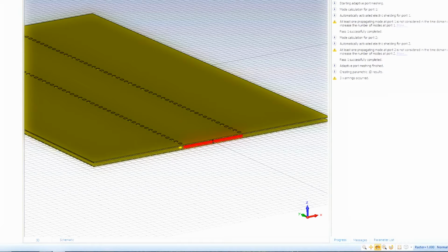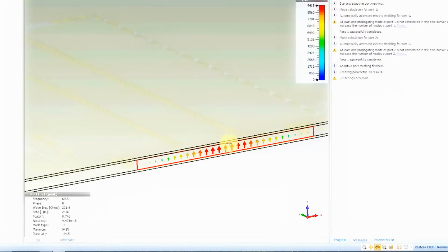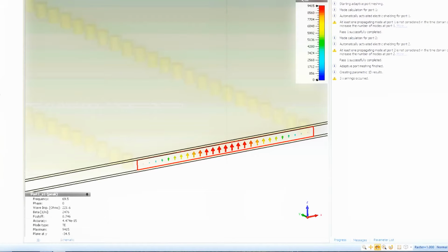Now, to see what it's got here in the 2D/3D results, port modes, port 1 or port 2 will be the same, E1. Now it'll plot me a little bit of an electric field, and that looks exactly like a TE10 mode. You'll notice here that the F cutoff is 8.7. So that means 8.7 gigahertz, and my SIW is far too wide if I wanted to go for 56 gigahertz. Similarly, E2 means the second mode. Now the second mode that will propagate, because the SIW is reasonably symmetrical, unless you deliberately excite it, will be a TE30 mode, and its cutoff is at 26 gigahertz.